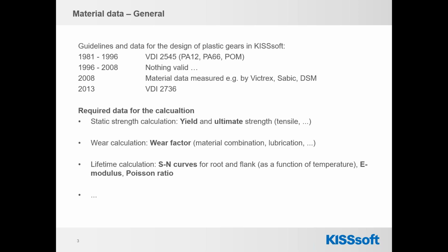Around the year 2013, the new VDI 2736 was released, and this is now the only valid guideline that we have to calculate the strength of plastic gears.